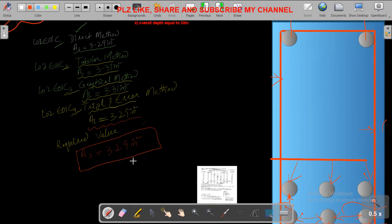In part C1 we also found the number of bars, that is, how many bars will give us this amount of steel. We found two best selections. The first selection is number 7 bar and the second is number 6 bar. This one will give us 3.52 square inches, while this one will give us 3.6 square inches.